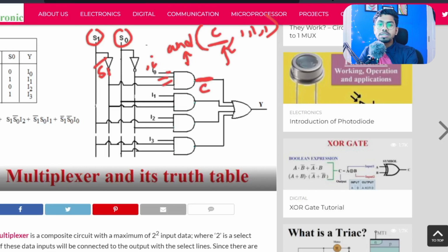For a multiplexer, for sure it will be simple, but any time your circuit has thousands of gates, writing your Verilog code at gate level is never a wise decision. So that's where we do behavioral description Verilog coding, where we just tell our Verilog simulator, hey, we need to achieve this thing, this is our logic or this is our algorithm, and you help us to synthesize it at the gate level and then further to the transistor level. That is not our work. Luckily, synthesis tools are intelligent enough to synthesize the whole circuit from the algorithm which we have written in Verilog.